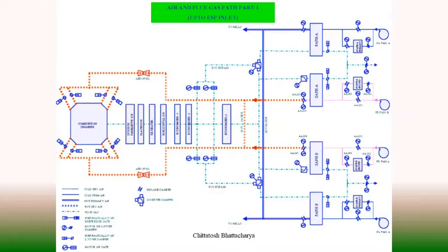But these flame scanners cannot work beyond a temperature of 90 degrees centigrade, so naturally they need cooling air continuously. So scanner air fans are provided to maintain the cooling of flame scanners. There are also AC and DC scanner air fans.